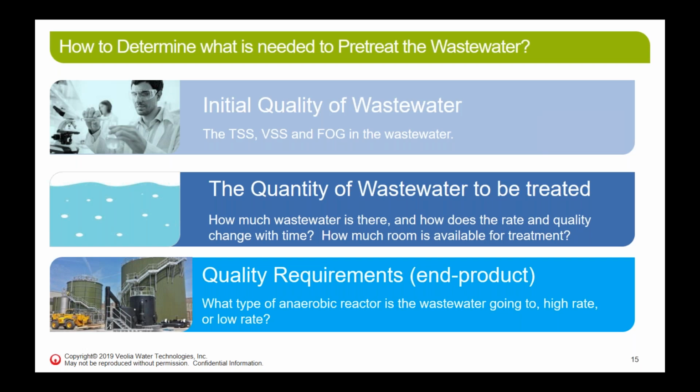We're talking about the quantity of wastewater treated, but we also want to talk about the spatial and temporal distribution of the water that comes in, especially when we're talking about equalization. Those factors are all going to be factored into the pretreatment schematic. So what kind of wastewater we have, what is the consistency and the constituents in the wastewater, and how are they distributed in time.